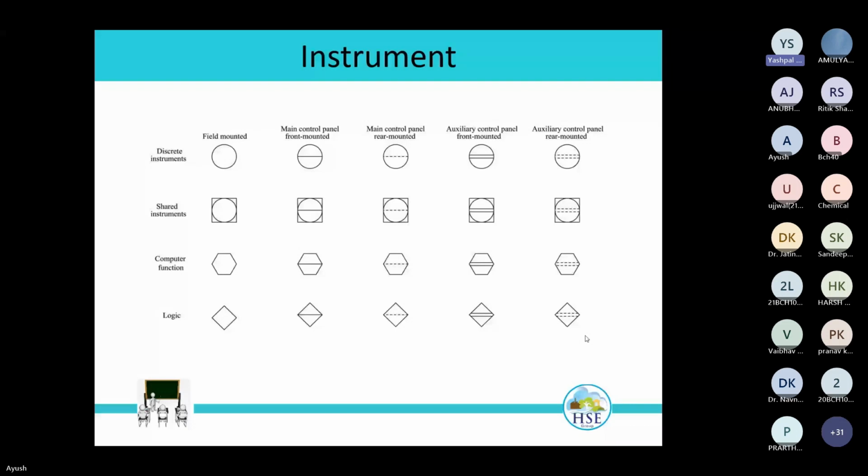All the logic means actions. Whenever our element sends something, if it only indicates, there is no action. An action can be an alarm, or a control action, like when we want to control a flow. The action can be transmitted to the control valve. So any action is through logics, and logics can be defined in this manner.